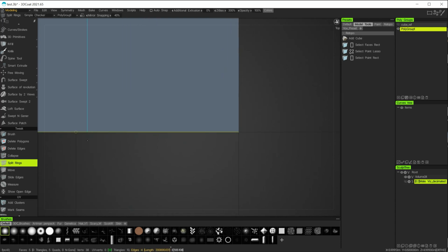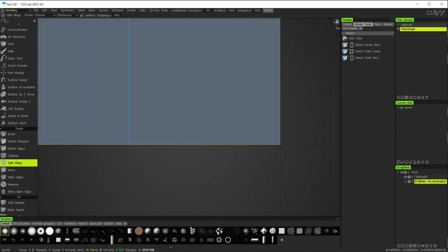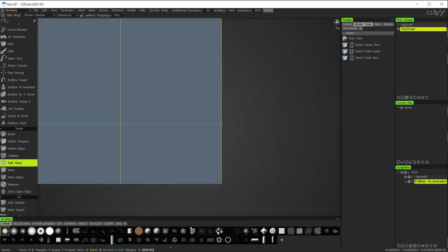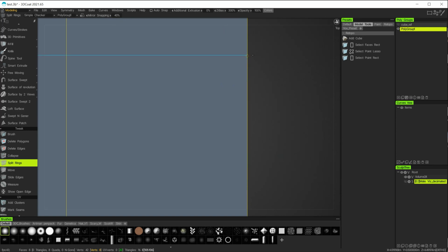You can see, because I've got the grid snapping on, that the tool is snapping to those increments. So at this point, I'll snap my first point to the 1/2 meter mark there. And on this side, zoom out, you can see my 1/2 meter mark there. It snaps to it. So I'll put another one right on there as well.